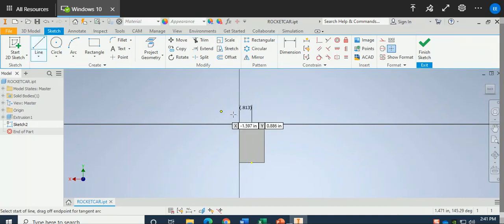And if you know what is correct, you start 1.5 inch. This line is supposed to be 1.5. So enter, enter. So this is approximately half of the distance from the top end. Now, the reason I drew this last line is because I want to establish the center point of the circle. So I'm creating a circle now, starting from the end of the line.